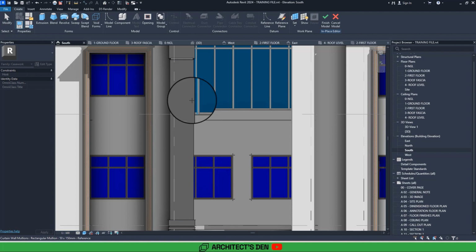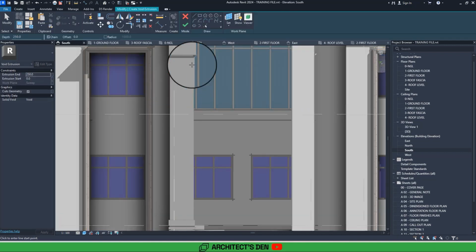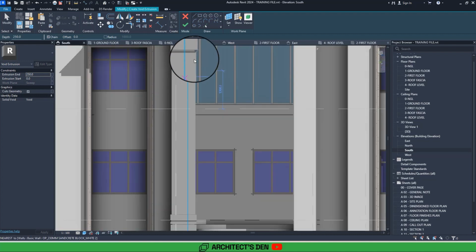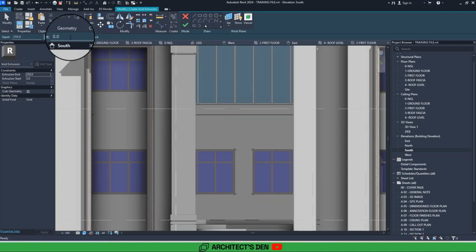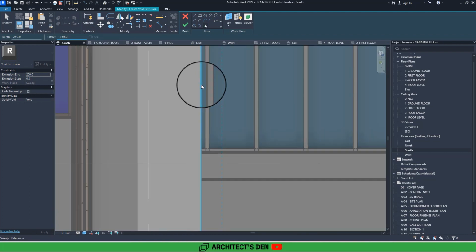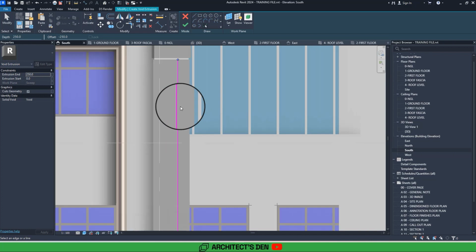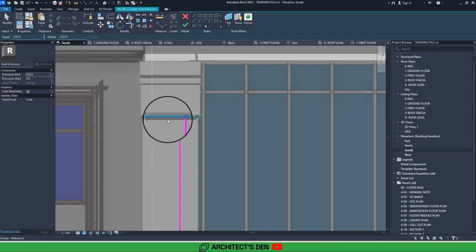Like I taught you about planes, when you go to the edge or the face close to the edge of the plane, you should see a highlight that has more than 2 perpendicular lines or parallel lines. So about that. So once that is done, I'll click on pick lines, set my offset to minus, let's say 250. And then when I click this edge, you can see the offset at the end, but I want the offset inside. So once it's inside, I'll press the tab key, or I can just click on it one after the other.